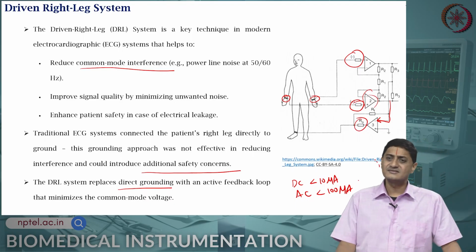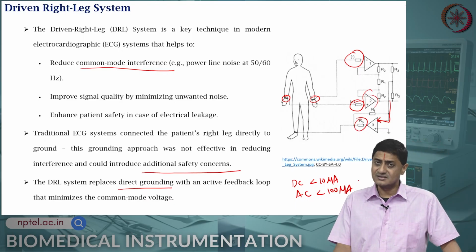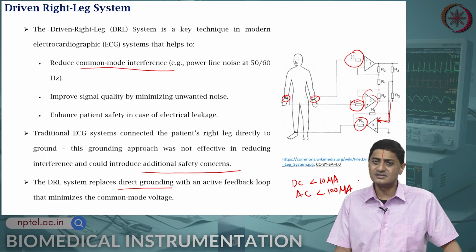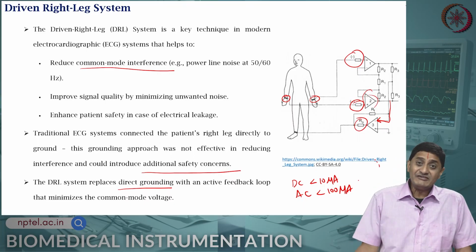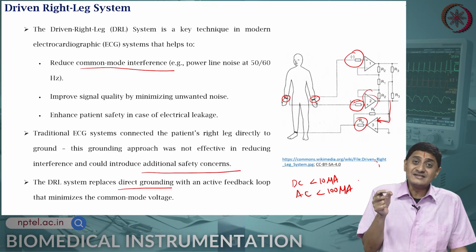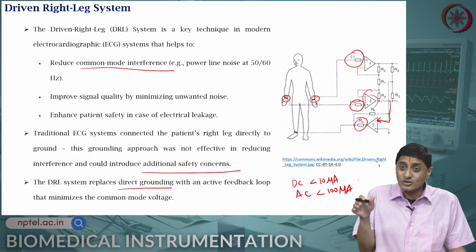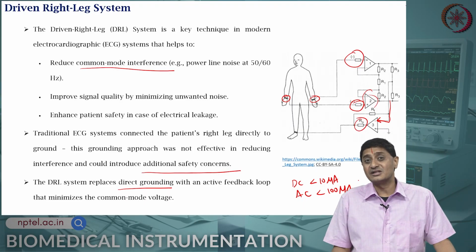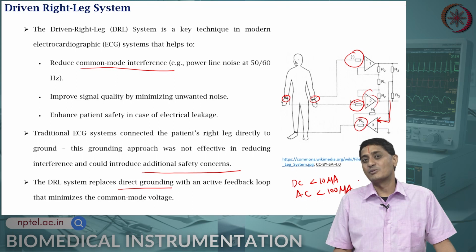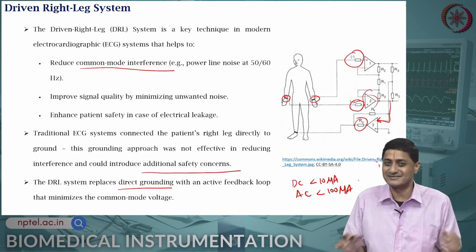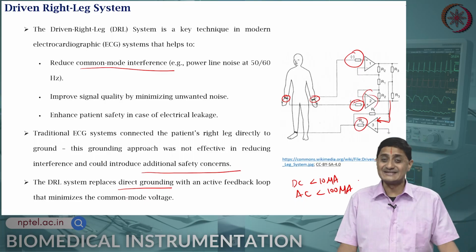Critical to this is the point that the common mode noise from both the left arm and the right arm is fed to the inverting terminal. That is absolutely critical. If the resistor values change slightly between the two op amps of the right arm and the left arm, then the corresponding potentials will change, and they will not be detected as common mode noise. So you need to have matched resistors, that is very critical in your design.